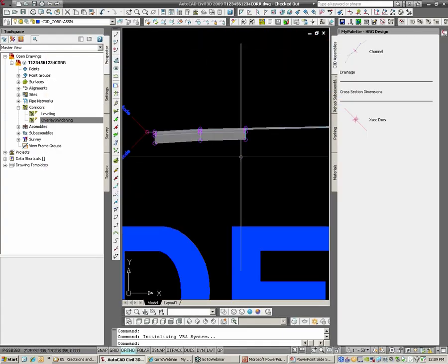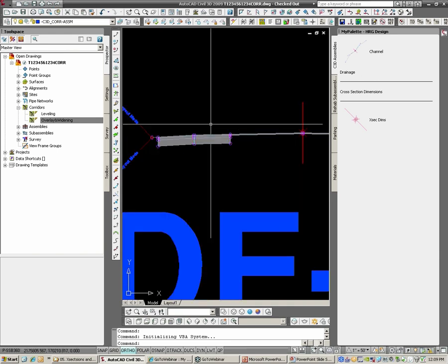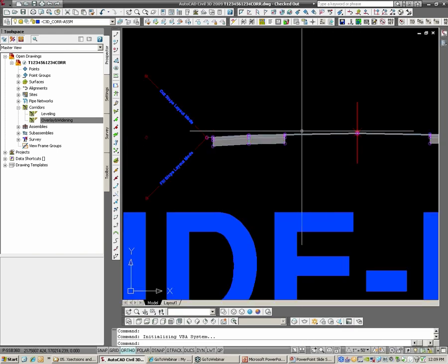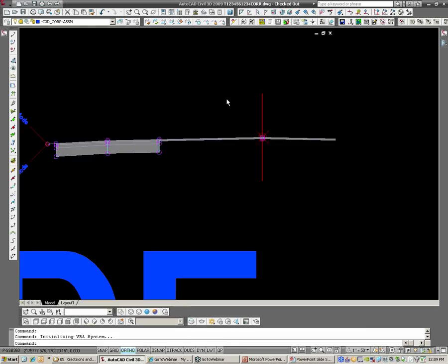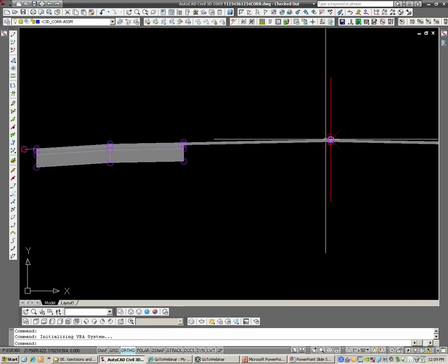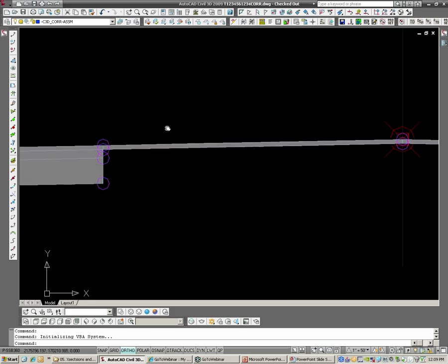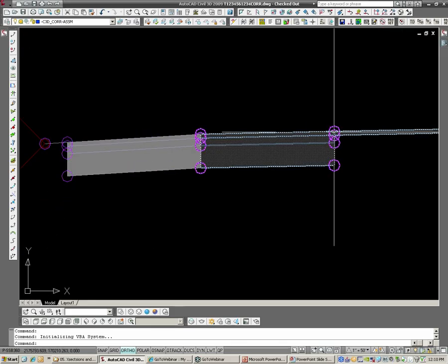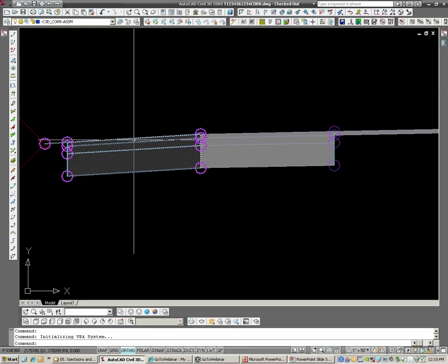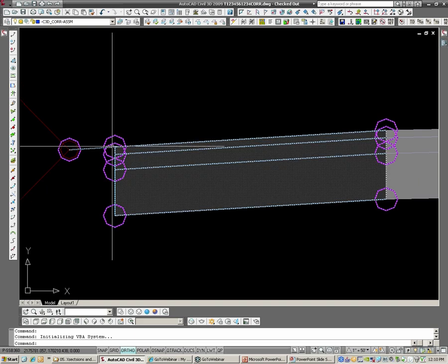And what that did is it made a surface, since we're using this assembly here as our reference surface. It made a surface that uses this link on the very top here, which is the overlay link. And how do I know that? Oh, I looked in the help. And it uses these links on the top for the pave, for the widening portion, and also the top link for the shoulder is also called pave. The surface will stop right here at the end of the shoulder because this link out here is called unpaved. This link right there, that line work.